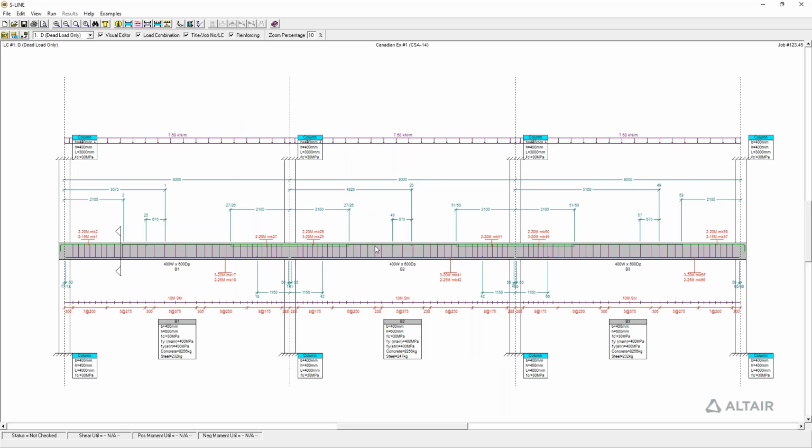So you can see here that it's initialized this data. It may not necessarily be exactly what we want to end up with, but it gives us a good starting point to start adjusting. So you can see that now we've got our stirrup spacing, our longitudinal reinforcement, our bar cutoffs, and so on defined based off of those initial parameters that we've set up. And we can fine tune that using the interface here. The visual interface allows us to adjust these dimensions, for example.